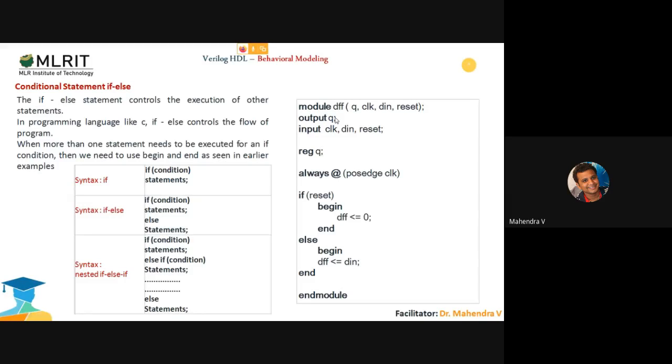The D flip-flop is a kind of storage element, and having the clock, we can take that as reg. And one more thing you have to remember: whatever constructs we are placing inside the always statement, all those constructs are of type reg, data type is reg. That means they have the capability of storing values or binary data.